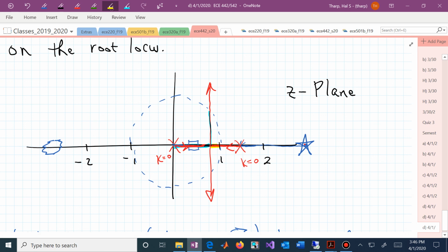And until we crank up the gain to get us to this particular value, we will stay stable. So up until we get to, and now I've run out of symbols, but let's just say that there is the gain k to get us stable. Then once we hit the unit circle positively or negatively, that's the maximum gain to stabilize this system.